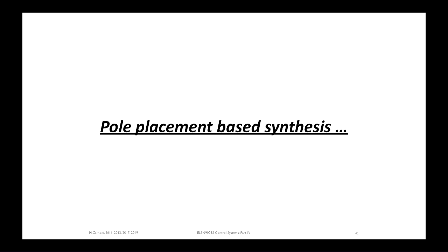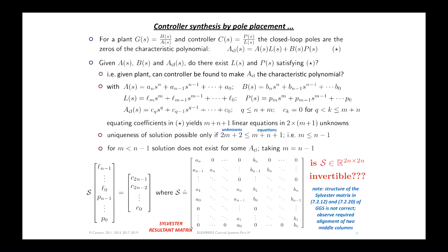As I've said many times before, control system design is not about recognising that for this problem I apply recipe A. It's about making use of all of your toolkit to address whatever challenge lies in front of you. So the basic idea in pole placement is to specify where you want the closed loop poles to be.